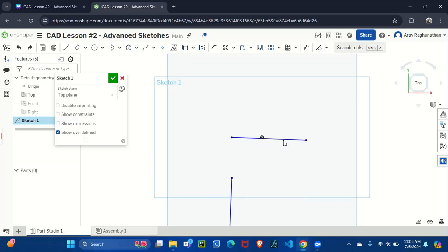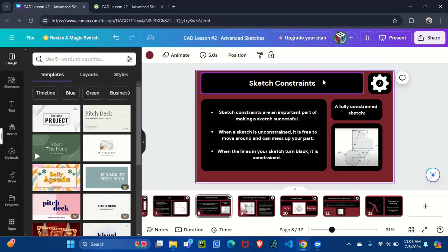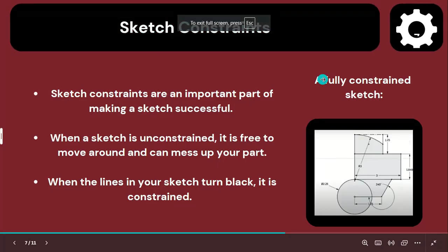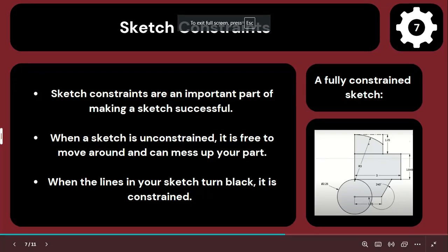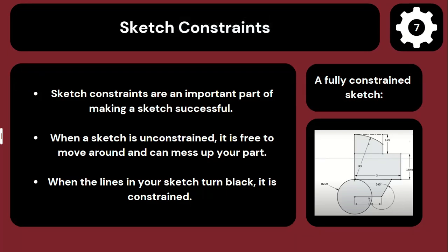These are just a few of many different types of relations you can create in Onshape, and these relations are really important for creating sketches. In Lambert Robotics, our CAD design team uses them all the time to create the wackiest sketches possible, and it makes our process really easy. Dimensioning is a great tool, but we don't have to keep dimensioning over and over again. We can just put two objects, relate them together, and then they'll be related forever.